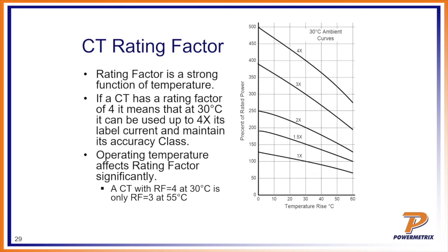So when you are sizing your CTs for these installs, make sure you take note of the temperature it is going to be in. If it's an outside temperature mounted on a pole, you're more likely to be able to handle that temperature range. However, if it's in a pad mount, you could have a little bit more problem because that heat retains in that pad mount cabinet.